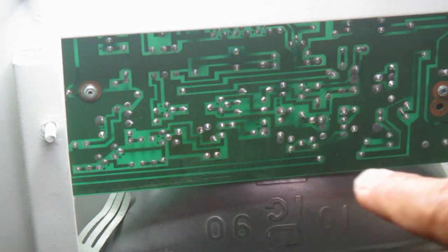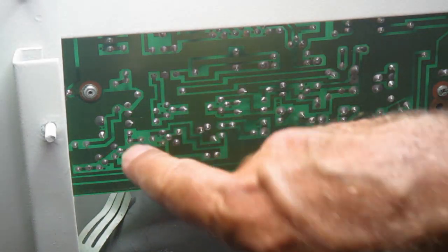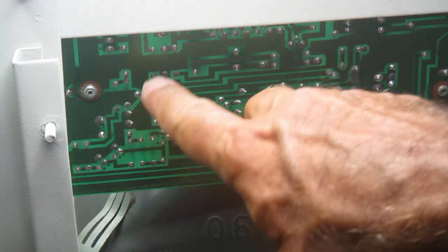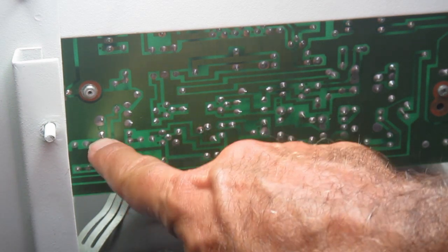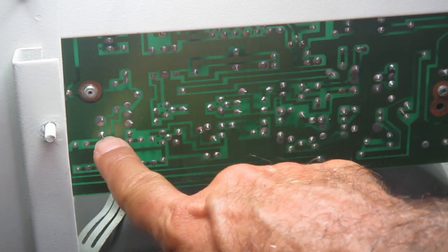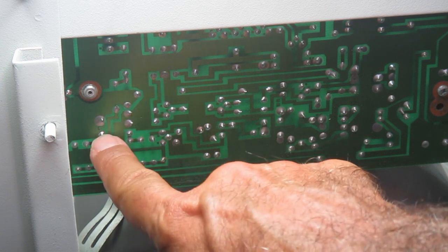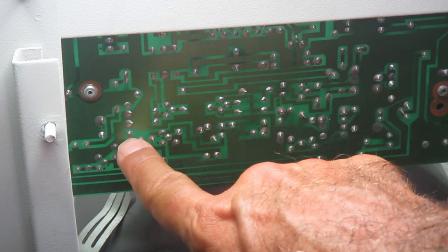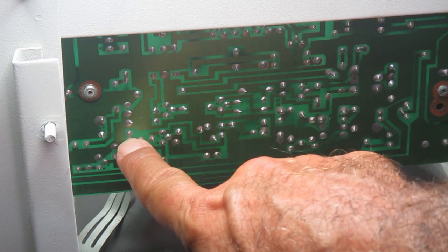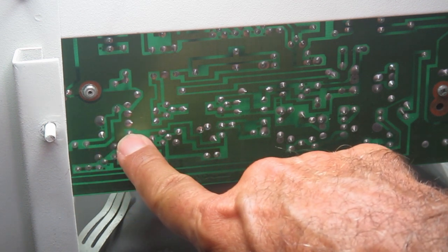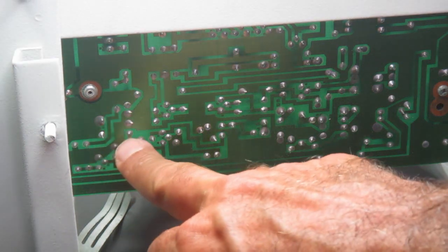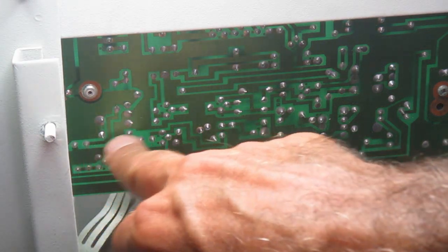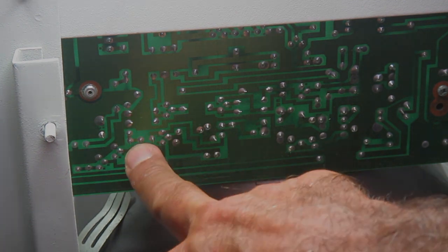Now since I didn't assemble the monitor, I don't need in this case to remove the PCB from the monitor case, and the resistor to remove is between these two solder joints. This one is the +12 and this is the other side of the resistor I want to substitute with the diode, resistor and capacitor combination to fix the monitor.